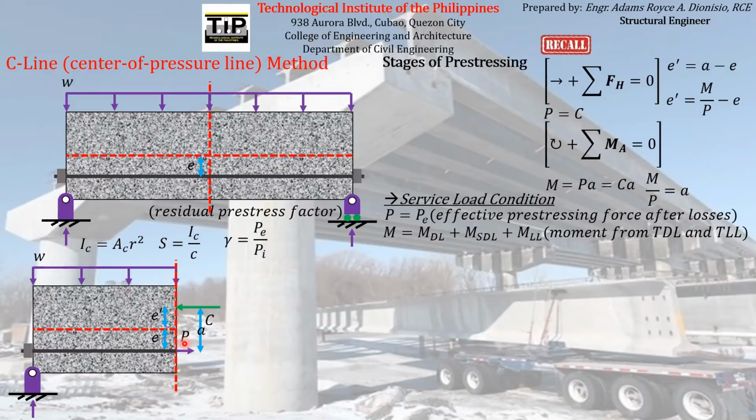So again, originally, if there are no external loads applied to the concrete element and the force acting is the pre-stressing force alone, we have seen from the basic concept method that the total compressive force is acting collinear to the line of action of the pre-stressing force here.